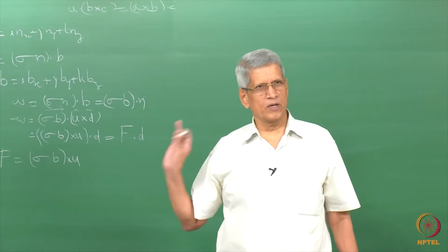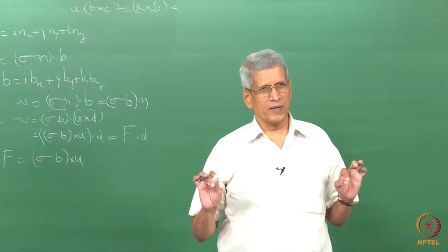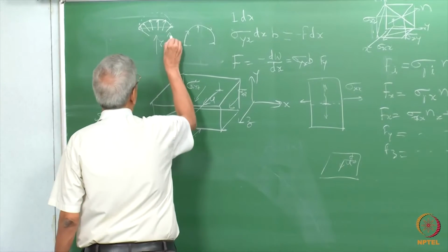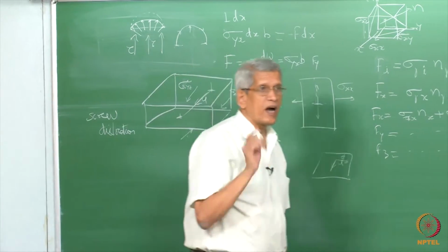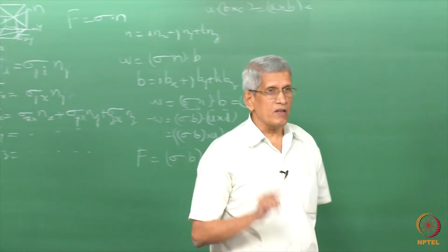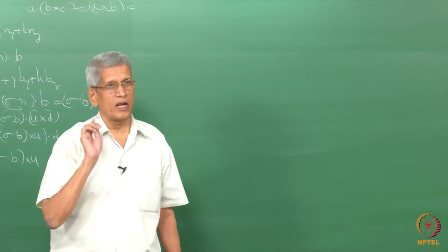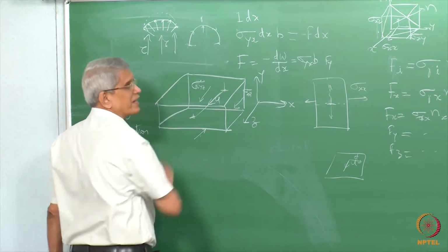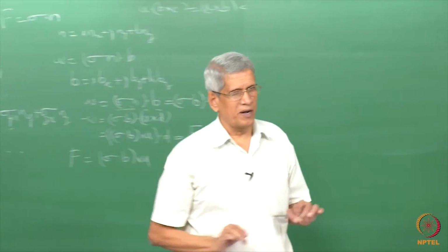This we will come to later when we talk about dislocation precipitate interaction, but what I wanted you to understand is that though the stress is applied in the same direction, this is the direction in which the external stress is being applied, the force which is acting on the dislocation because of the external stress is always perpendicular to the line direction. Because of that, this part may move in this direction, and this part may move in this direction in the expansion, correct? So this is something very significant which one should understand.